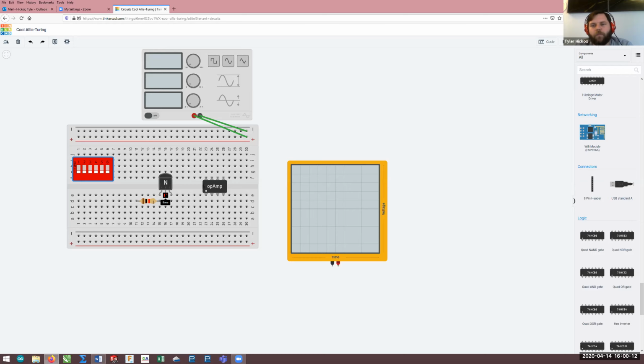We let the students pick materials to test, and we've actually said no more Snap-on tools, as they're just not allowed. They have too high a chrome and vanadium content, so they'll chew through bits when they try to get machined, or they'll even max out different loads. So no Snap-on tools.